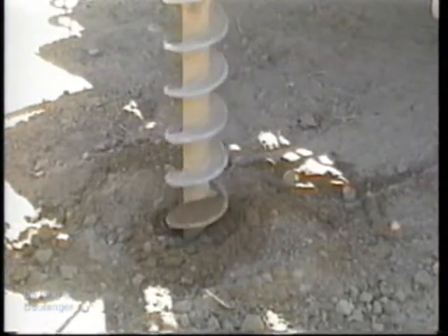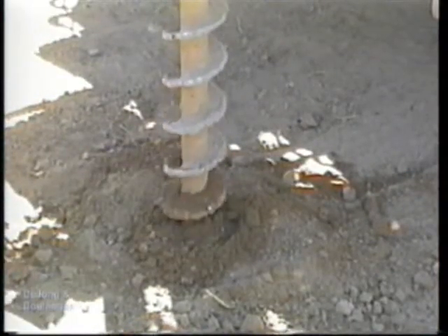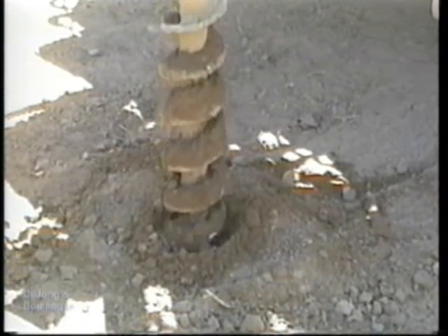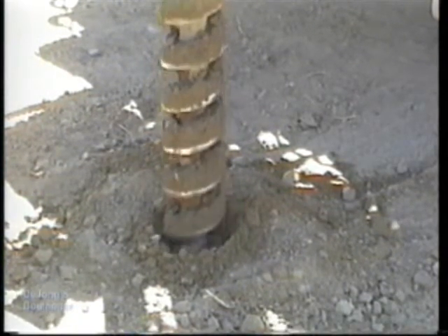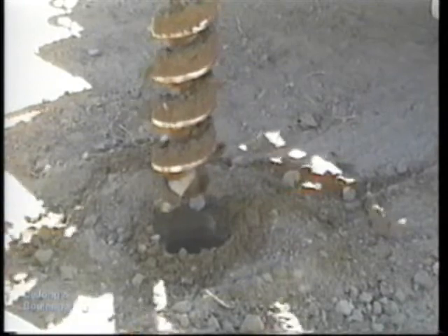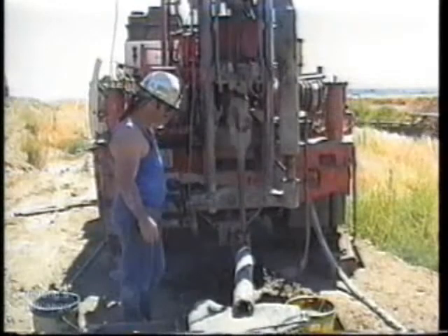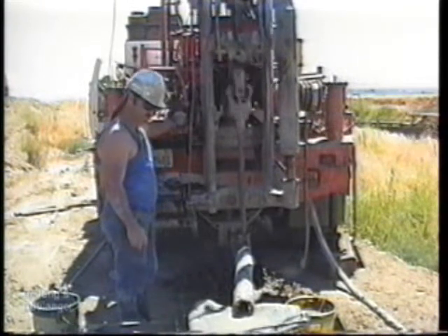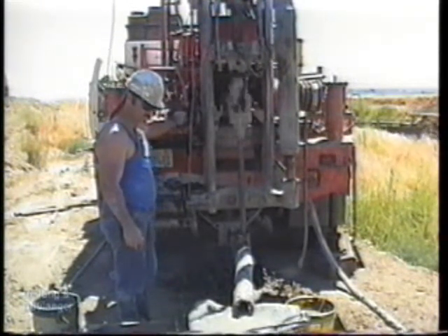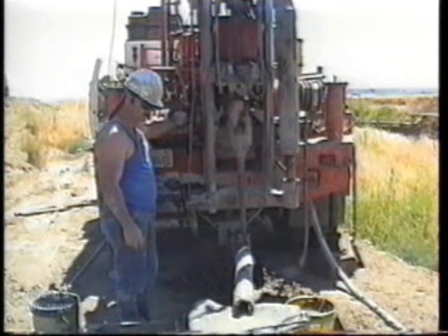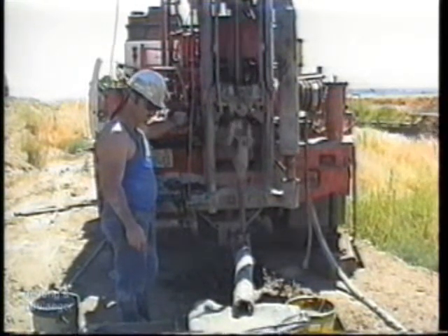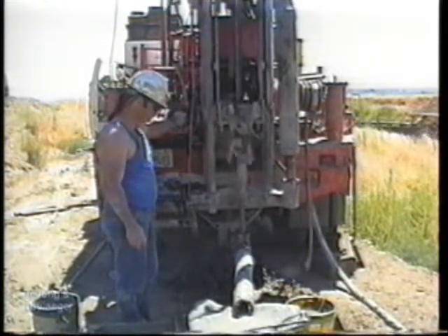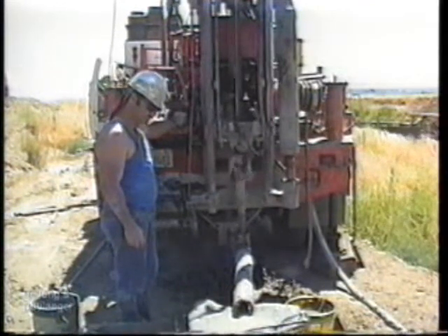It is recommended that the diameter of the borehole be 4 to 5 inches. As the diameter of a borehole is decreased, the penetration resistance is likely to increase. Side discharge bits should be used when rotary drilling because the jetting action of a face discharge bit disturbs the soil at the bottom of the bore hole.